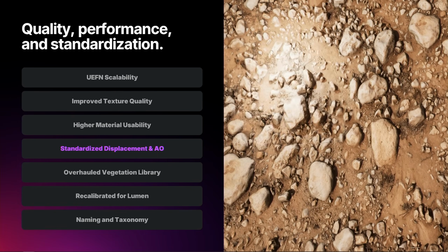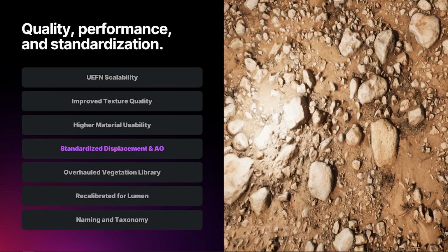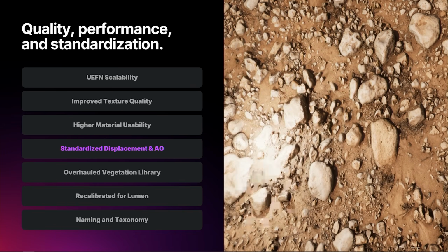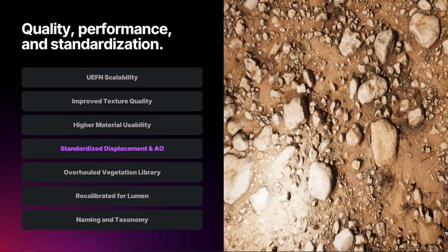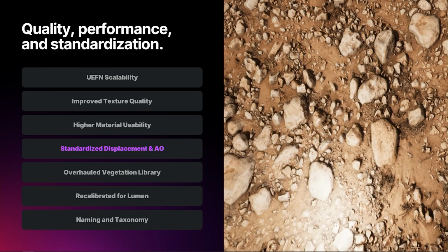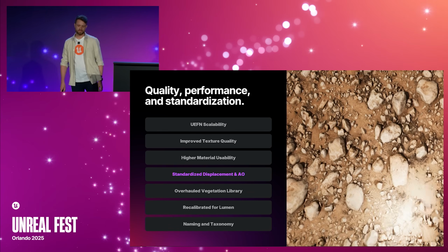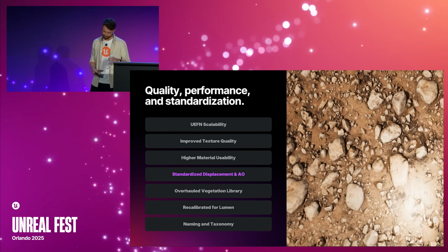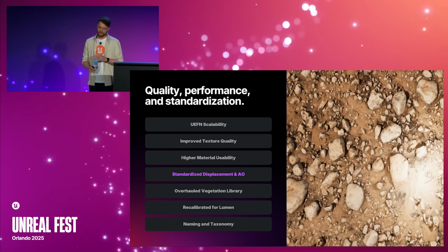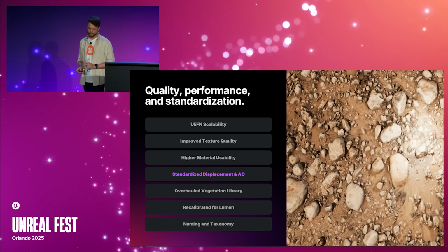For surface assets, it's important to consider the original scan dimension because the calibration relies on the asset's physical size. You can think of a texture UV tiling as the XY dimension and a displacement strength as the Z dimension. The assets will look their best when the tiling closely resembles the physical scan dimensions. These dimensions can be found in the metadata of every surface asset that we provide in the library.